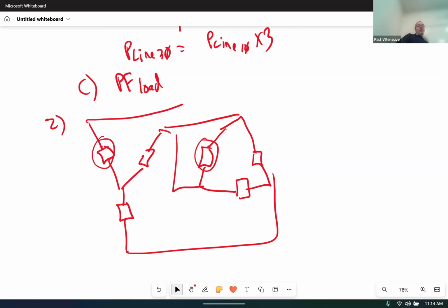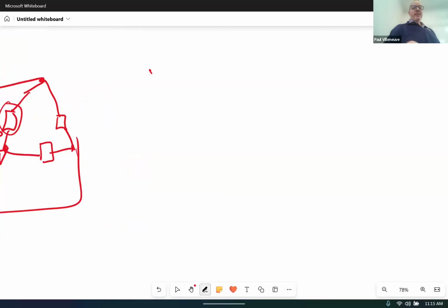We want to deliver nominal or rated voltage. Is this load ZY in parallel with Z delta? Meaning they have to have two common nodes. Is this node and this node the same as this node and this node? How about even over here, this node and this node? Well, this one looks good. Check. But let's follow this one through. Oh, I've got another resistor go through. So those aren't in parallel with each other. So you couldn't come up with an equivalent impedance unless you did this.